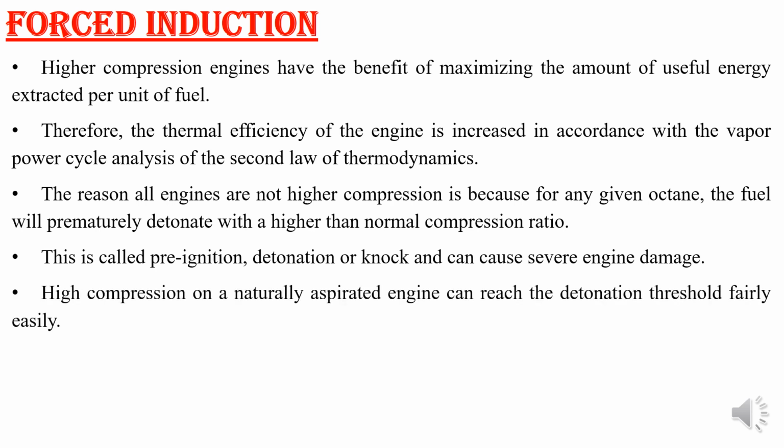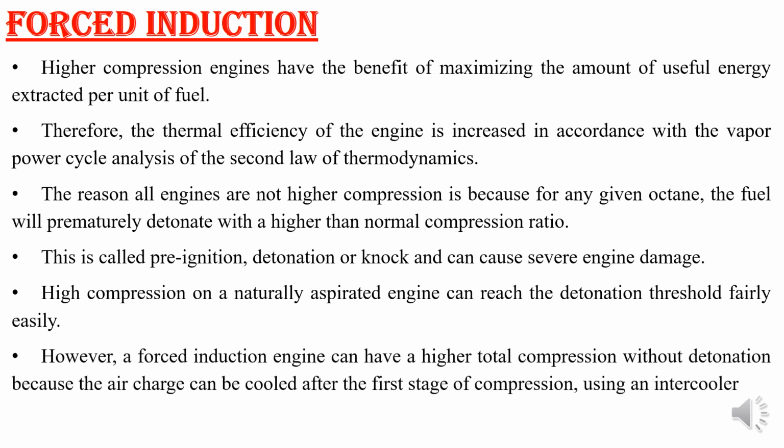A high compression naturally aspirated engine can reach the detonation threshold fairly easily. However, forced induction can have a higher total compression without detonation, because the air charge can be cooled after the first stage of compression, that is by using the intercooler.